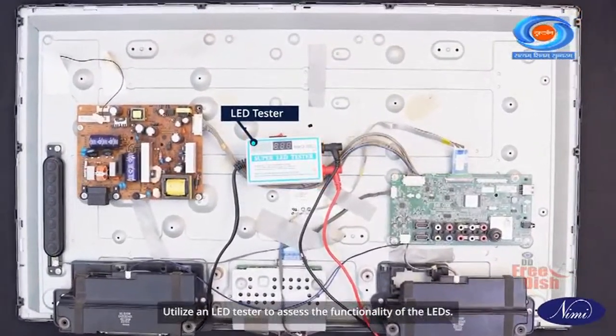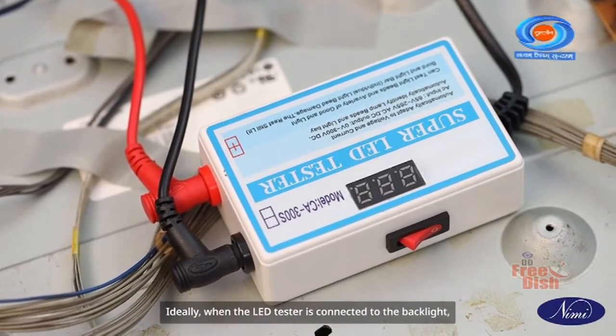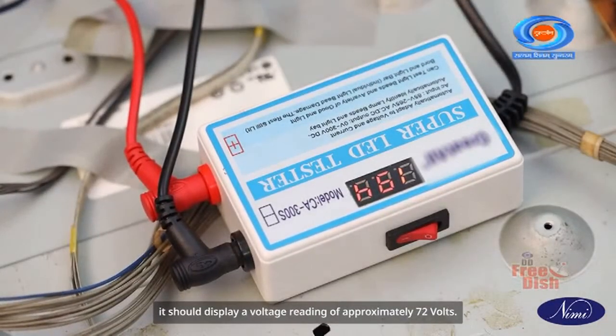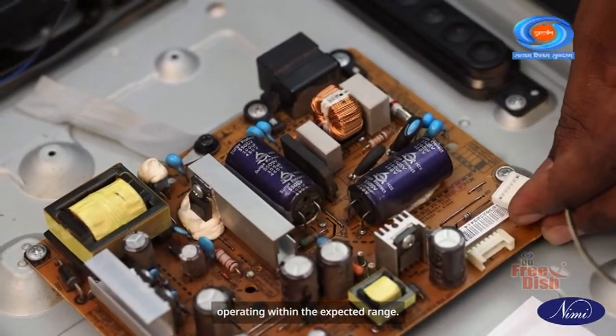Utilize an LED tester to assess the functionality of the LEDs. Ideally, when the LED tester is connected to the backlight, it should display a voltage reading of approximately 72 volts. This voltage indicates that the LEDs are operating within the expected range.